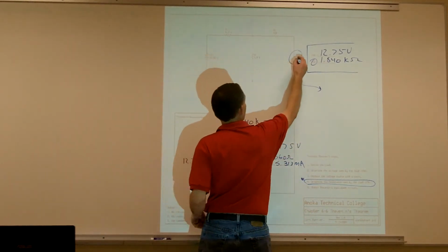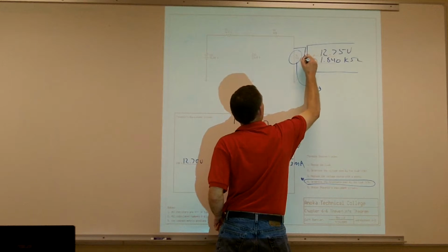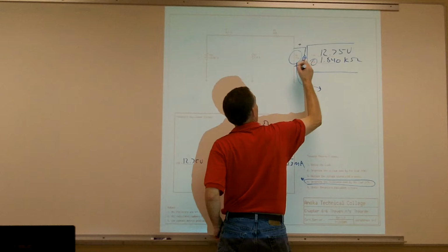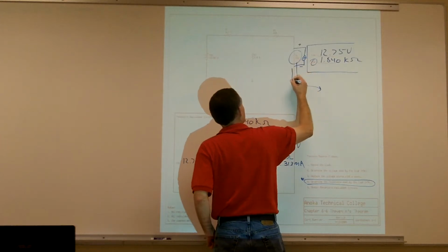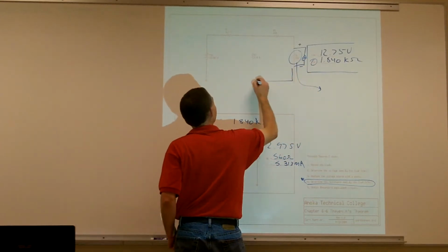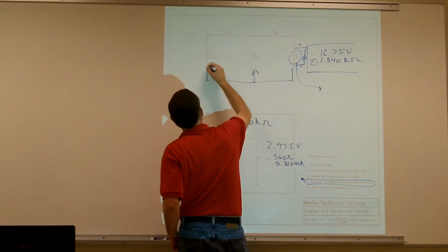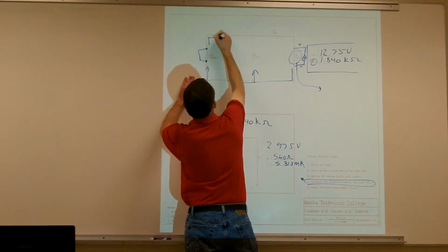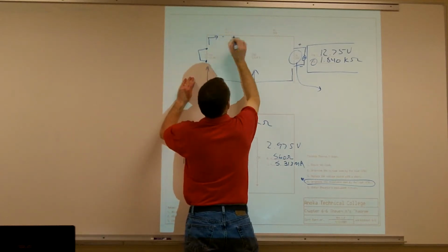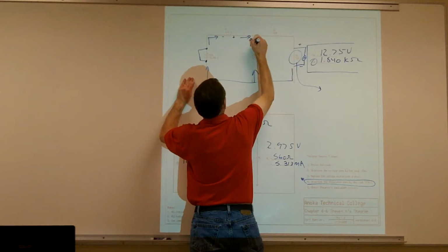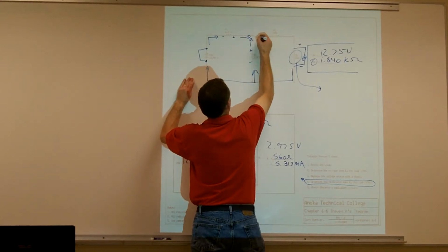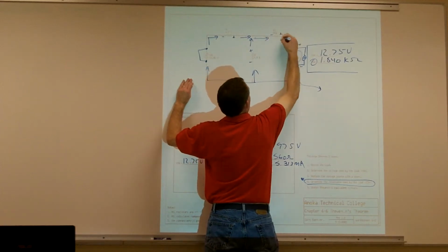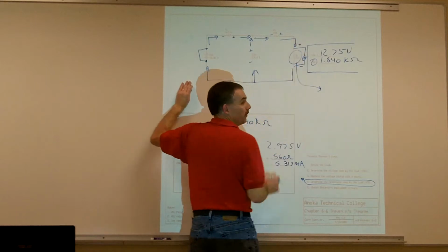So we're going to just replace this with an ohm meter. Now our ohm meter is kind of just like a power supply. So if I'm going to put this one as positive, negative, all my current is going to come out of my ohm meter. It's going to go through the grounds. Some of the current's going to go this way, some of the current's going to go through this way, and I got my shorted out power supply here. And this current's going to go through here. Then it's going to join in at this point here. And those two currents are going to combine and go through R3 and then back into my source, which is what I consider my ohm meter.